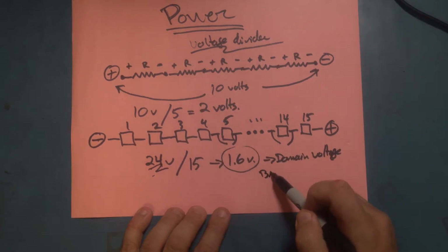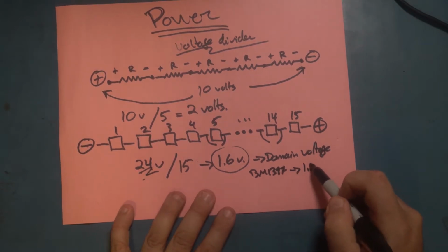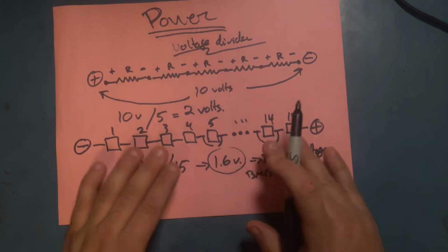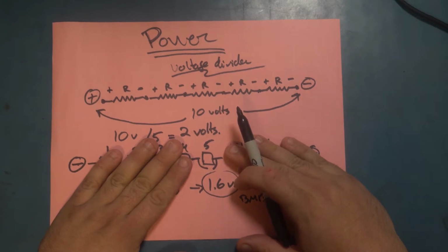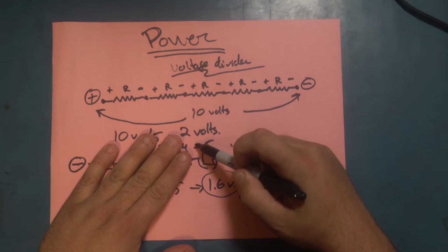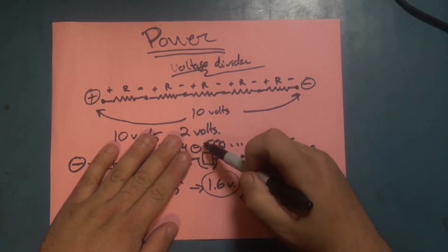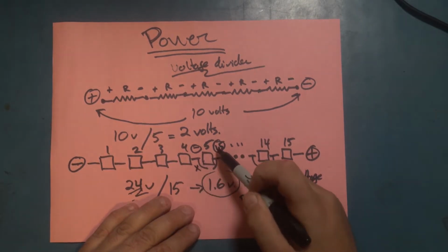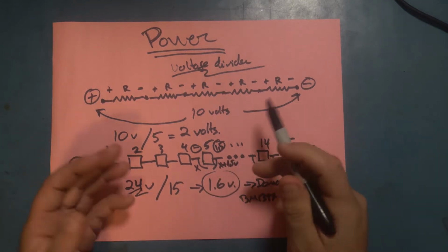has a BM1397 chip, it should always be around 1.5 because that's the working voltage of that chip, right? And so for any one chip, if we look at our chip number 5 here, whether you have a real ground on one side and 1.5 volts on this side, or in this case a certain voltage X on one side and X plus 1.5 volts on the other, the chip doesn't care.